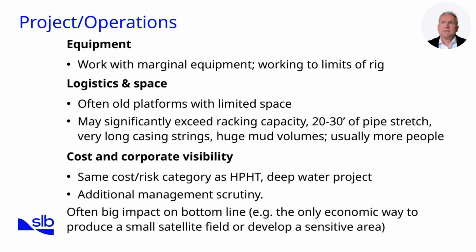When planning ERD projects, we often find ourselves working with marginal equipment, pushing rigs close to their design limits. Many ERD wells are drilled from older platforms where space and deck load capacity are restricted. This creates real challenges in logistics, pipe handling, and rig up. One issue is racking capacity. With long casing strings, we may need 20 to 30 feet of pipe stretch just to accommodate the length and weight. Mud volumes are also significantly higher, and with larger teams on site, operational efficiency becomes critical.